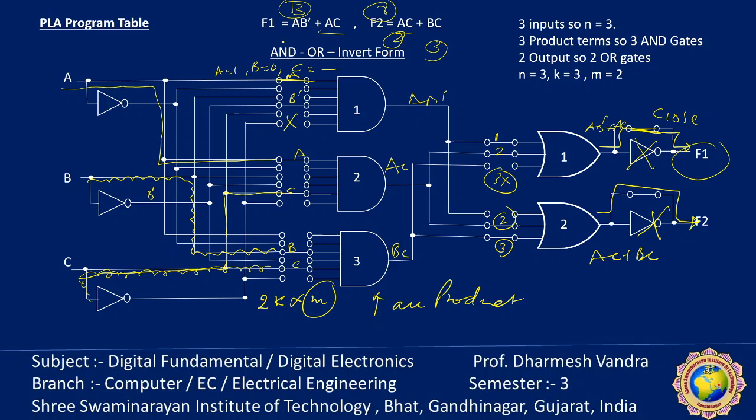Okay, suppose there is a ROM, then 8 gates are required. The circuit is reduced by more than 75% in the first level. Similarly, at the output also, the circuit is reduced by more than half. So PLA is for a specific application, and this can be done by simplifying each function to the minimum number of minterms. Okay, it might be we have to consider the complement sometimes. So the number of literals in terms is not important since all input variables are available. Both the true value and the complement function can be simplified to see which can be expressed with fewer product terms, and provides the product terms that are common to more functions.